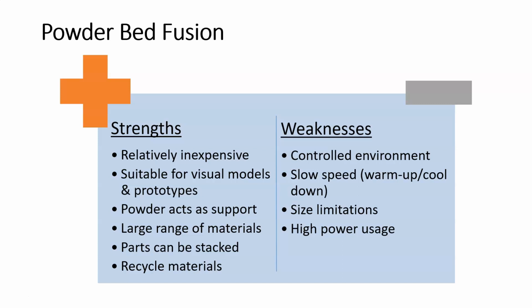It's typically a very slow speed process. It takes a long time to heat up the reservoir and the supply. It takes a long time for it to cool down, especially in the case of metals. This can take hours, or in some cases days. You do have size limitations. The build reservoir is not so large. Typically, and we'll see some actual numbers here, it's on the order of a 6x6 or 8x8 square at its largest.